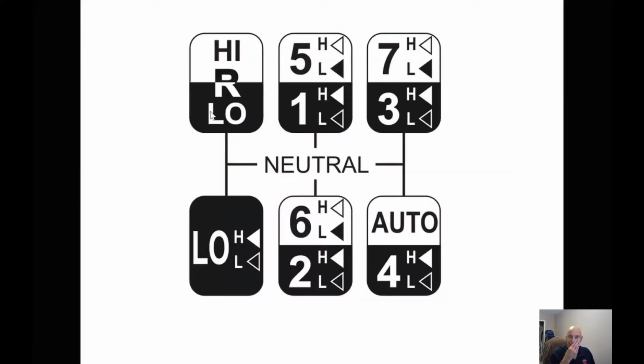Now we talked earlier about taking a look at the shift patterns, and again, every vehicle will be different, so understand how they're set up. When we were talking earlier in the transmissions about an overdrive, what they used to have was a setup like this, where low was first, then we went second, third, fourth, fifth, but with an overdrive you went 3, 4, 5. And that's why if you take a look at the underneath of the new shifter, they have it set up so that you go 3, 4, 5. We'll talk more about that in shop when we're looking at the top covers.